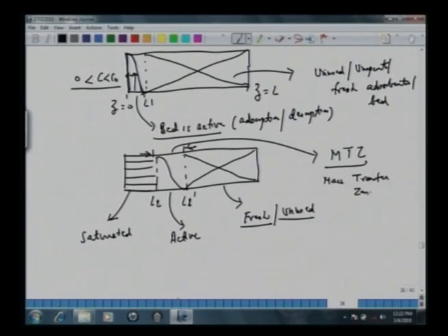It's a zone or certain region of this packed bed column which is dynamic in nature. It's moving from here to here. It's a very thin region, and the regions ahead of this are completely saturated, and the region after this is fresh, where the activity of adsorption and desorption has not yet arrived. So this is the region of mass transfer zone. We will see its significance in the next slide.